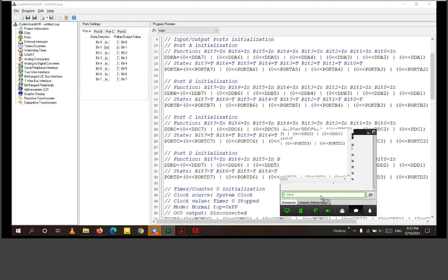The other means tri-state, or high Z, high impedance. We said pull-up is internally connecting to VCC by a resistor. Tri-state is not connected to anywhere. Tri-state means three states: not connected, from outside connected to 0, from outside connected to 1.